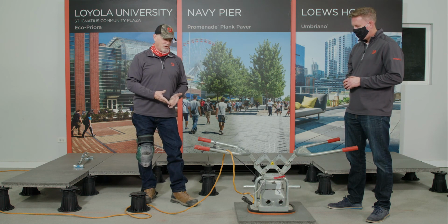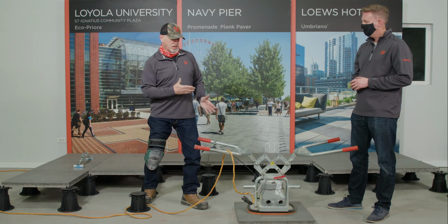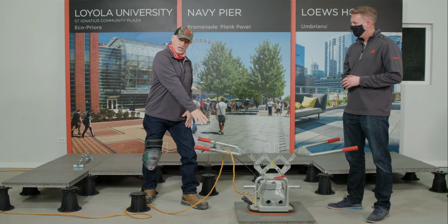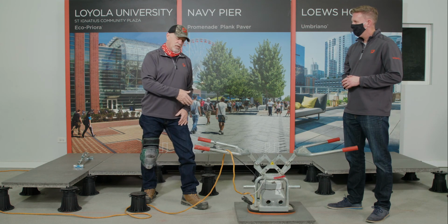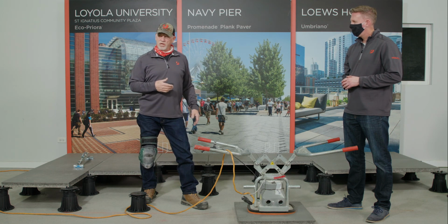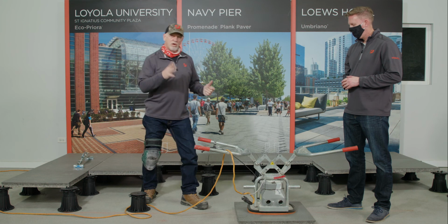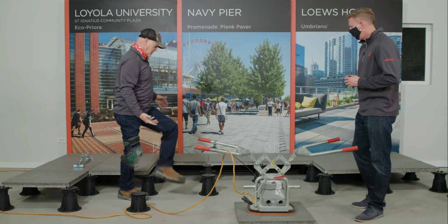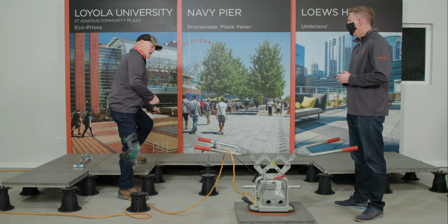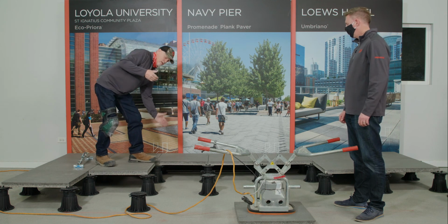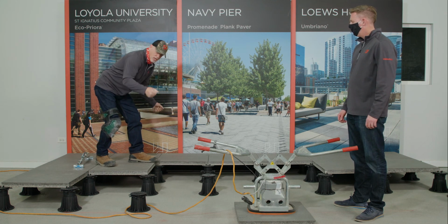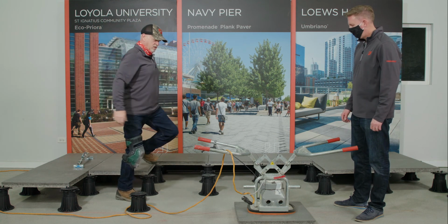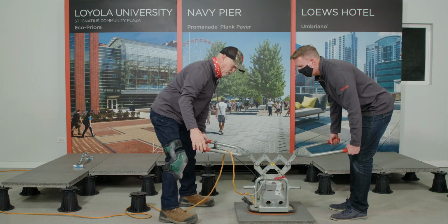But these electric vacuum systems are great. The nice thing that I like is that between two people, we're dividing the weight of that slab. So here, with a 2x2 slab weighing in at 96 pounds, Brad and I are going to split that weight in half and install that. What's important with this tool too is that we communicate on how we're going to install that. So we're not wrestling each other as we set that in, we've decided that we're going to set in low point first here into the tabs and then rotate that slab down into the fresh pedestal, if you will. So with that being said, power on.